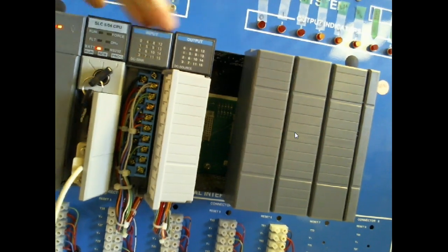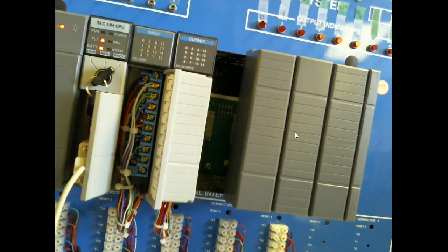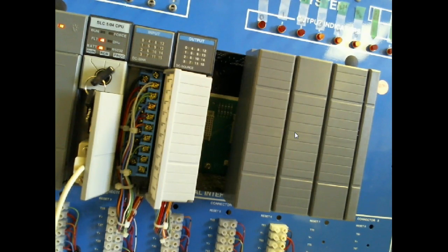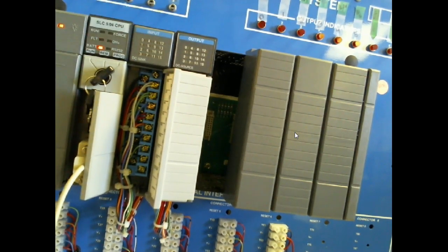And you don't even have to use 0 and 1. You could come out here and start at slot 7 and work towards slot 1 if you wanted to. It's just that when they set up this trainer, they decided, which is obvious, to use slot 1 and slot 2 for the 2 I/O modules that they provided with it. But it's actually up to you. You could have a communication module here. So if you wanted to communicate with Ethernet, then you can buy a communication module and not do the RS-232 anymore.